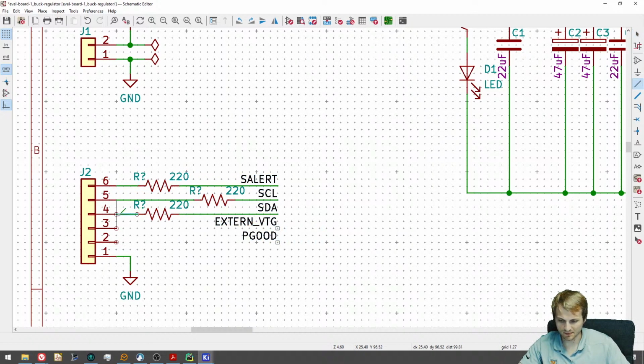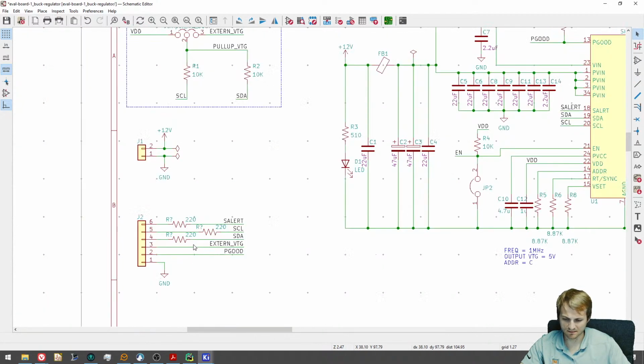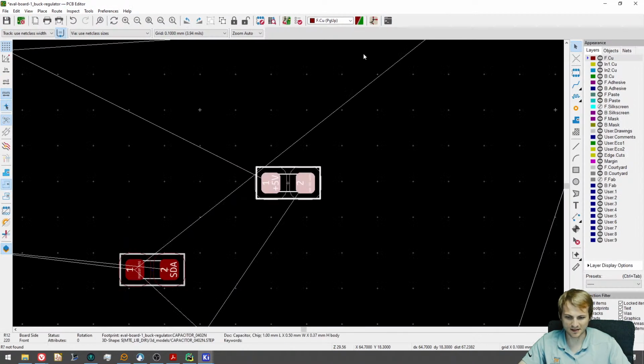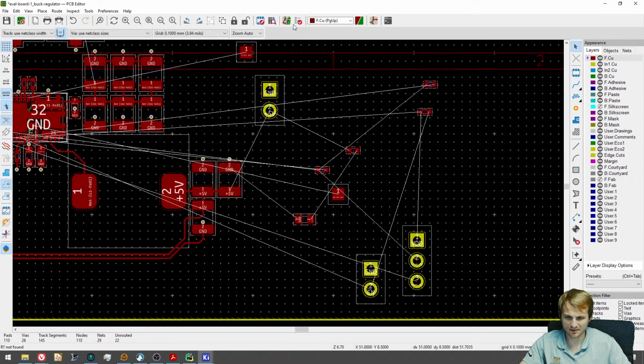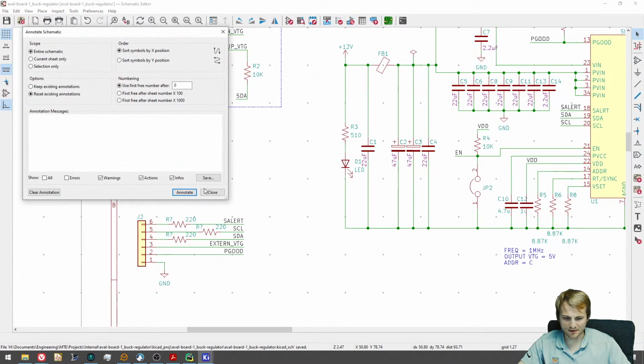But if it's between the diff pairs, then technically it still is to ground. It seems to be a feed forward capacitor. Yeah, but if it's a feed forward, that would essentially be injecting some ripple in there, which is funny because they're quite adamant that you don't have to.